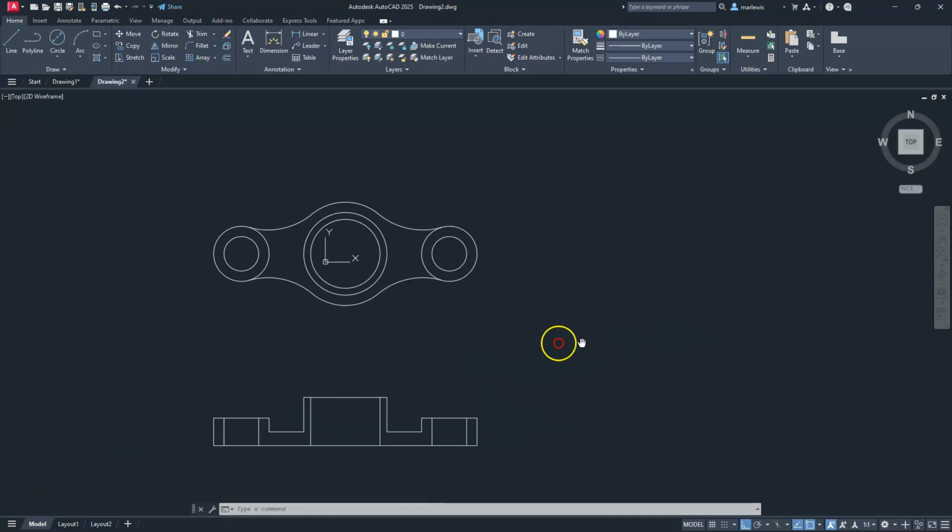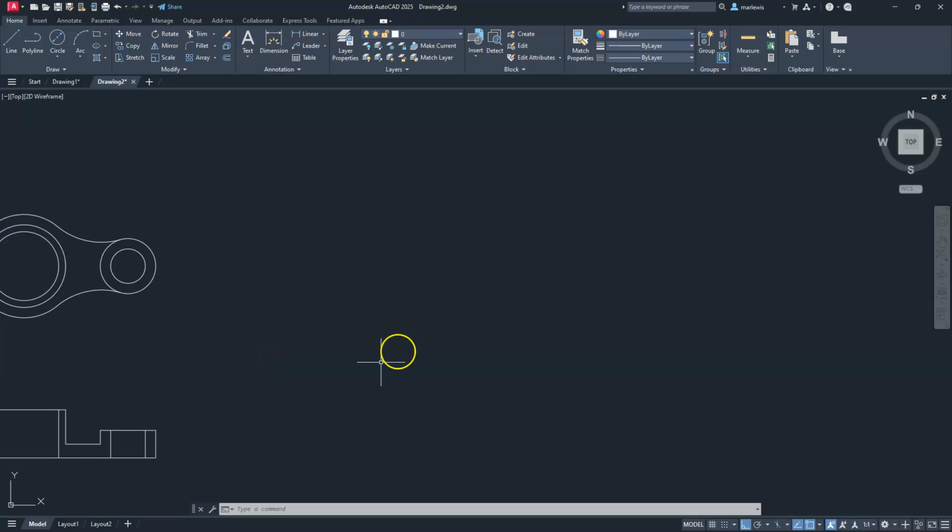Okay, so let's go ahead and give ourselves a little real estate here. And then we're going to start off by creating this. Remember, we have to use the ellipse command. So EL, enter, then I enter. Oh, it won't let me do that, and you'll notice that that error is not letting me select the ISO circle. I kind of jumped the gun on it. I need to tell it that I'm going to create an isometric, so I'm going to select that icon here. And then we need to switch to isometric top. And now we should be ready.